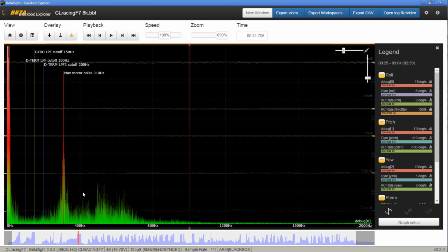Now we have that whole 32K, 8K mode coming into play, right? So you've got to pick which one. In 8K mode, you're going to need less filtering because the gyro is doing it internally. And that's, again, the argument. From what I've seen, the gyro is doing a pretty darn competitive job for how much latency you're getting. It's doing a pretty good job of filtering out the noise. But in 32K mode, it drops off. We can do a pretty good job too.